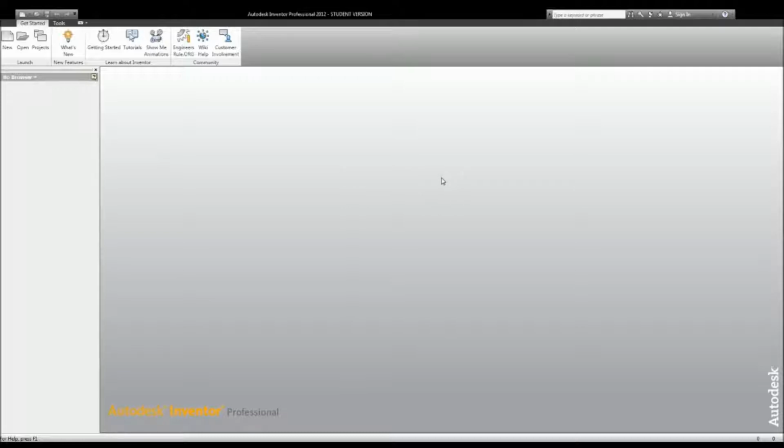so the various files are important. Okay, so you can tell by looking at the image what they kind of mean. So these two files here are blocks, while these two files are stacks of blocks. So what this is, you're assembling these files together into one bigger object. This file here is for looking at an orthographic view of your object. Okay, so go to standard.ipt, open that up.